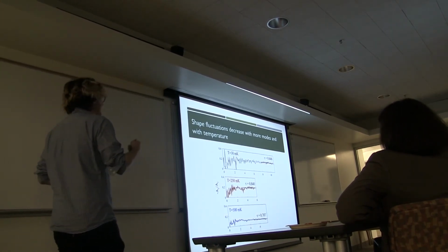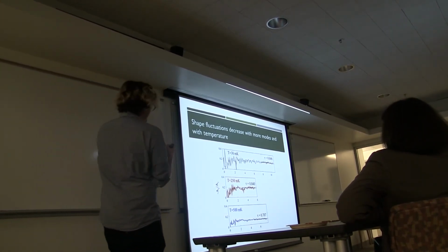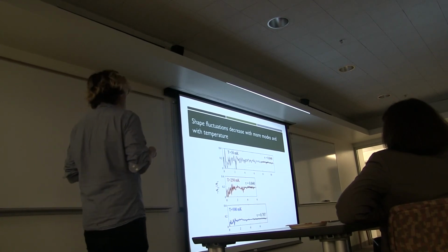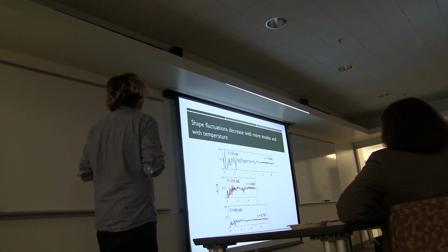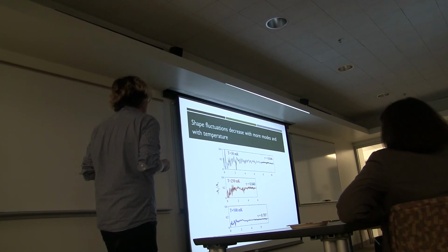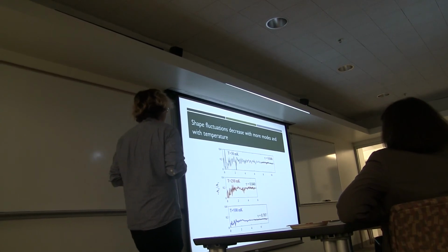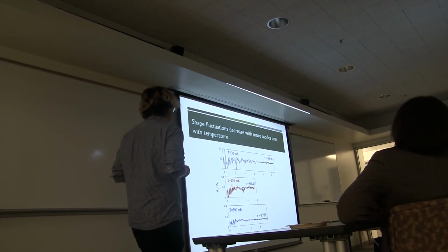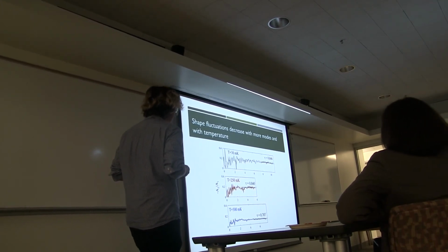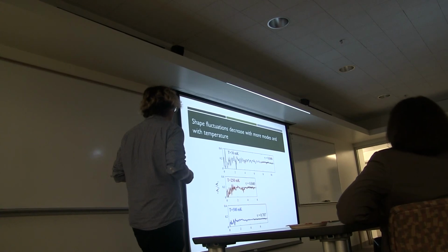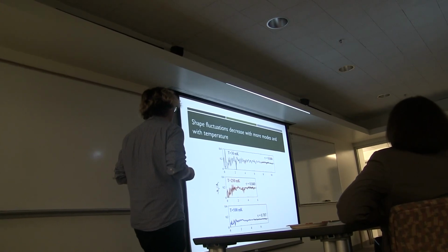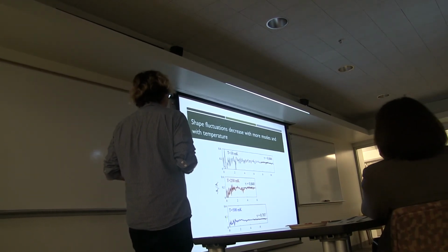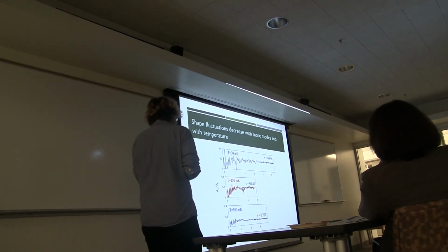The first is the fact that the fluctuations decrease as a function of gate voltage as we add more modes. So what I've done is I've swept the gate at different temperatures, and what we find is that the scale of the fluctuations decreases as we go to higher temperatures for similar gate voltages. Here I've taken where the critical current first becomes non-zero and subtracted it. This value is slightly different between the data sets.